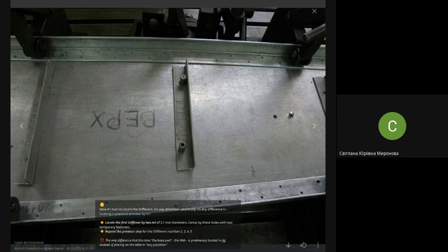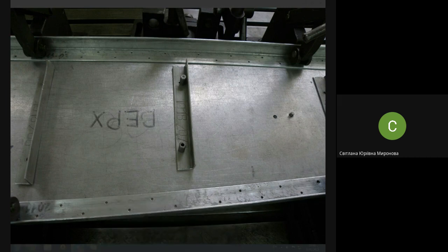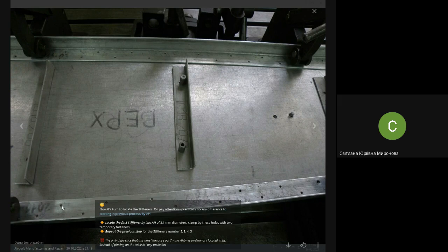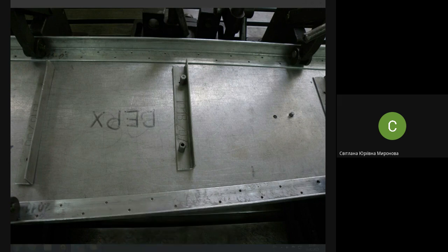Secondly, this CFH hole or base hole is much greater in diameter than any holes for riveting. Usually they are diameter 5 or diameter 8. We studied this even in third year. And a pilot hole usually has a diameter of 2.6, the minimal possible diameter for the minimal possible rivet.